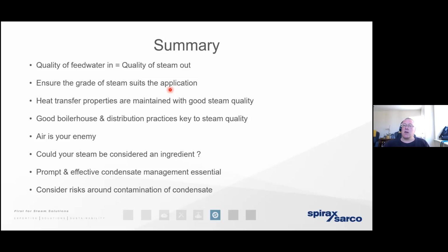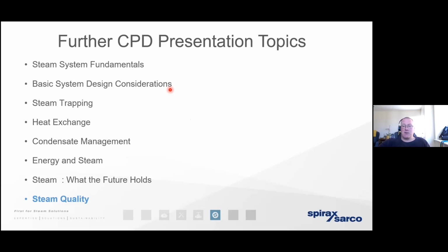And the good news is we can increase the efficiency of the lesser sophisticated range of controls that furnish the boiler very, very easily. We can retrofit upgrades in a minimum of downtime. Please remember that wet steam and air are perhaps the biggest enemies of a well-designed steam system, regardless of whether we're talking about process steam or plant steam. But please also give thought to the value of getting that condensate away from the process and getting it back to the boiler house.